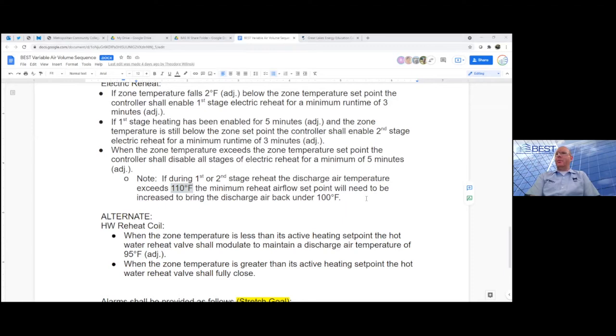It's kind of weird. They work better with water, as Ted mentioned, because it's easier to pump. It's also much more BTU dense than air, so that's much more effective. But trying to do it with air, unless you've got a specific reason you need to do it that way, it's not an effective approach, generally.